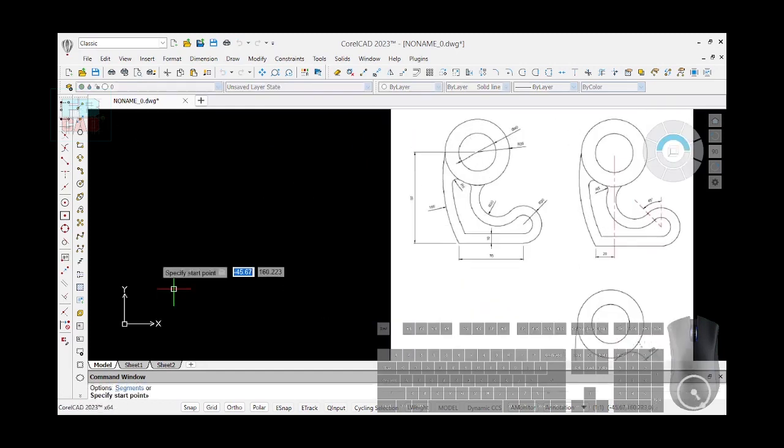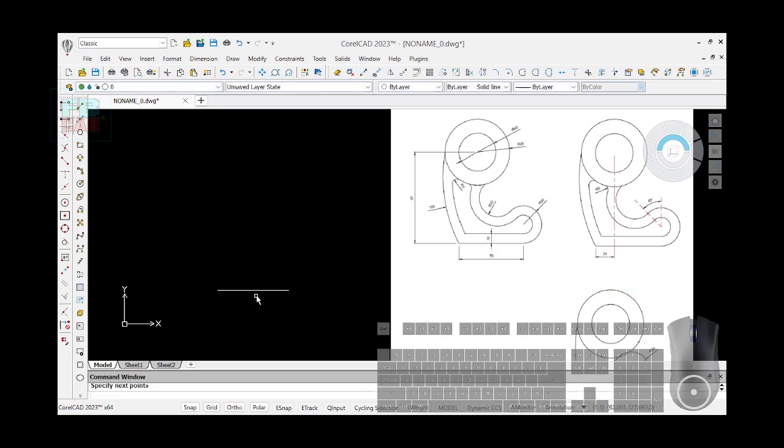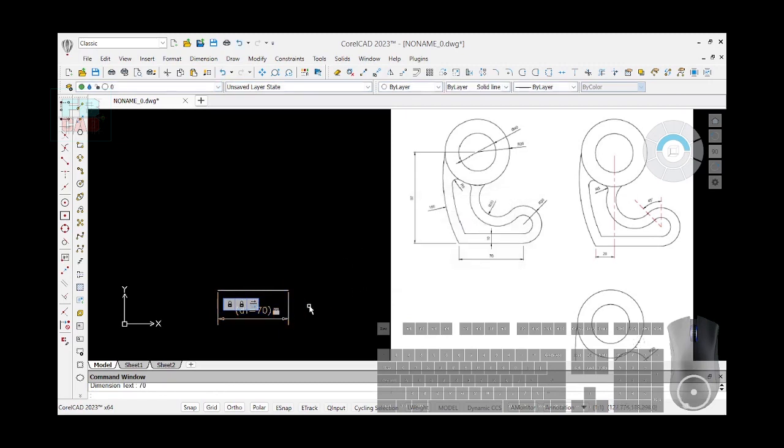We take our straight line, then we'll make a horizontal line. Take it from here. It's the line of 70, perfectly horizontal. Enter. A geometric constraint. Want it horizontal. Geometric constraint, want it fixed. Fixed. Okay. Now dimensional constraint. Linear. Pick here and here. 70. Okay, we have 70.